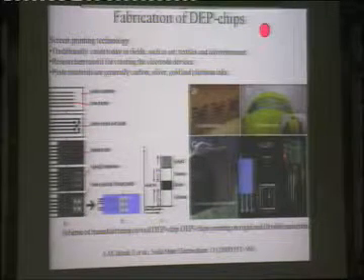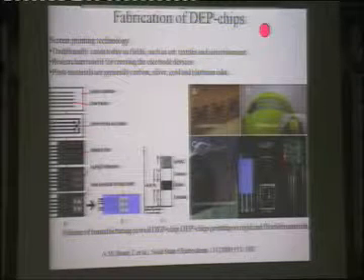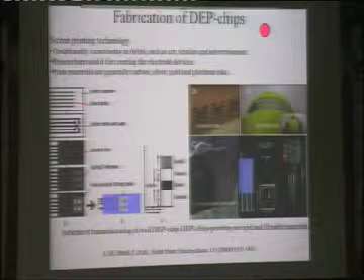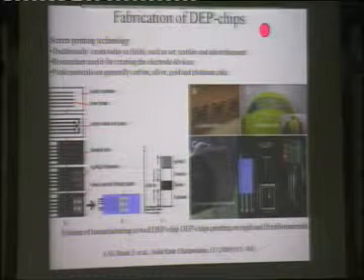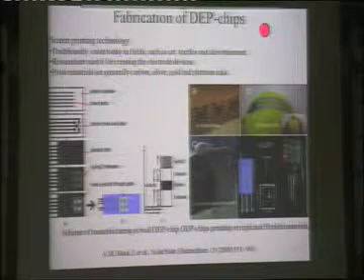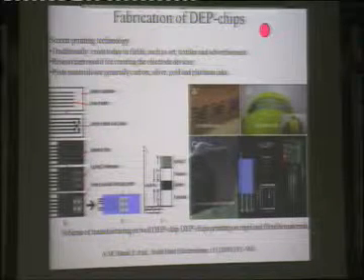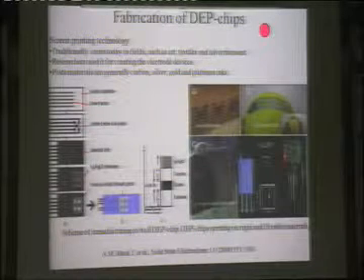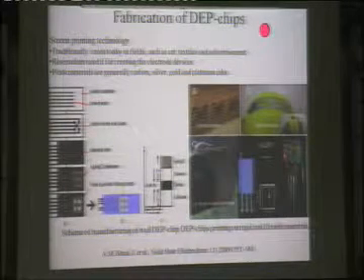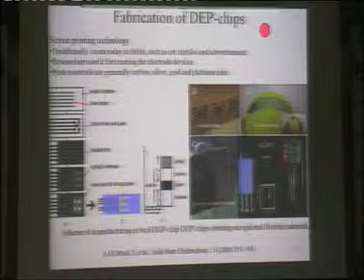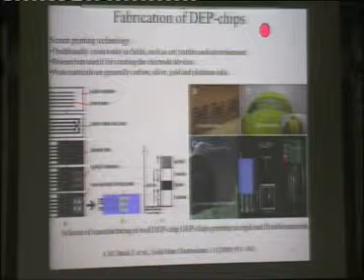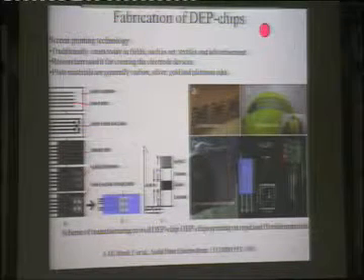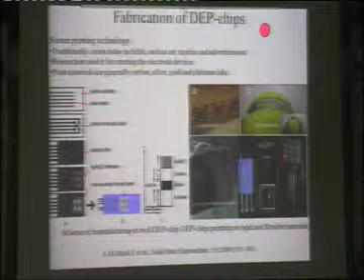Now here we will talk about the disposable electrode printed chip, or DAP chip for short. This chip is very small in size and has electronic properties, and it has three electrodes: the working electrode, reference electrode and counter electrode. The material generally used for the working electrode is gold, carbon, platinum or silver, according to the analyte we want to analyze.